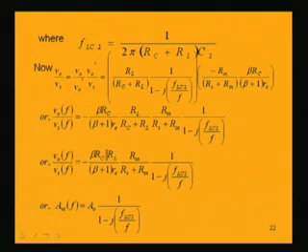Now, if we look into this numerator, the portion Rc into RL by Rc plus RL can be written as Rc parallel RL. So, in the numerator we have minus beta into Rc parallel RL divided by beta plus 1 Re, as it is we will be writing. The rest of the part is R in by Rs plus R in into 1 by this quantity.